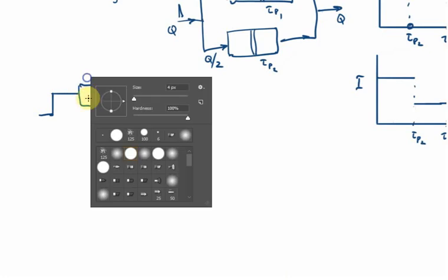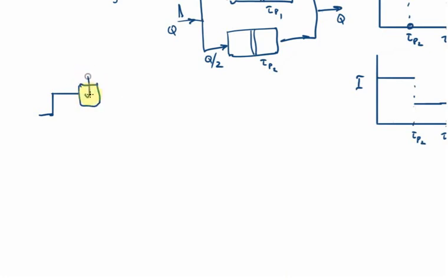So we've got two CSTRs. And again, we'll apply tau p1 and tau p2, or rather, in this case, we'll call it tau s for stirred tank, tau s1 and tau s2, which are generally different. And again, we can assume perhaps the flow rates are equal, but this volume is greater than this volume. So this space-time is greater than this space-time.